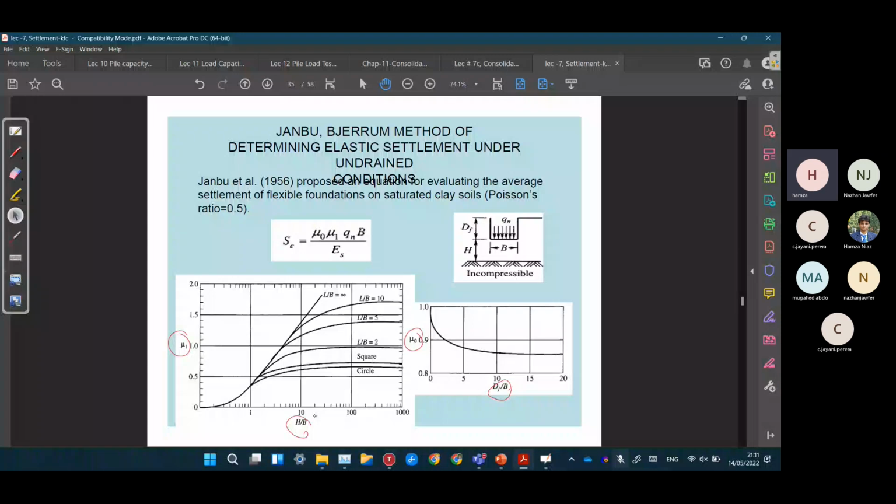So we are assuming that for clay strata, up to this 2/3 of length, the load varies with the slope of 1 horizontal and 4 vertical. So up till this 2/3 of length, the slope is varying as 1/4.